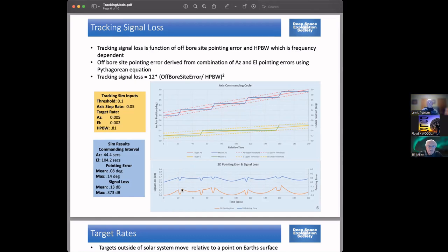And so just to explain the patterns here, it's not just random noise. It occurs in a very periodic way. Basically, when you're going through the drift phase, you drift from a maximum error, through where the object's very near the boresight, which gives you minimum error, and then you back out to the other boundary.